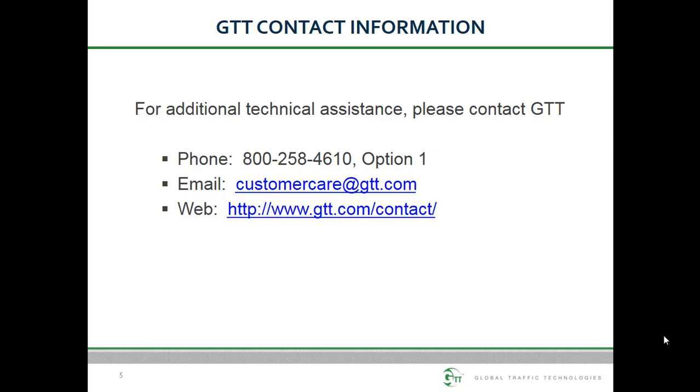In both cases, it is strongly recommended that an earth-ground connection be made for the cables that go out to the field. These earth-ground connections will help protect the Opticom equipment as well as other equipment in the traffic cabinet. See the installation instructions for details on these earth-ground connections. For more information about cabinet and controller interfacing, please refer to the GTT customer portal or contact GTT Tech Support.